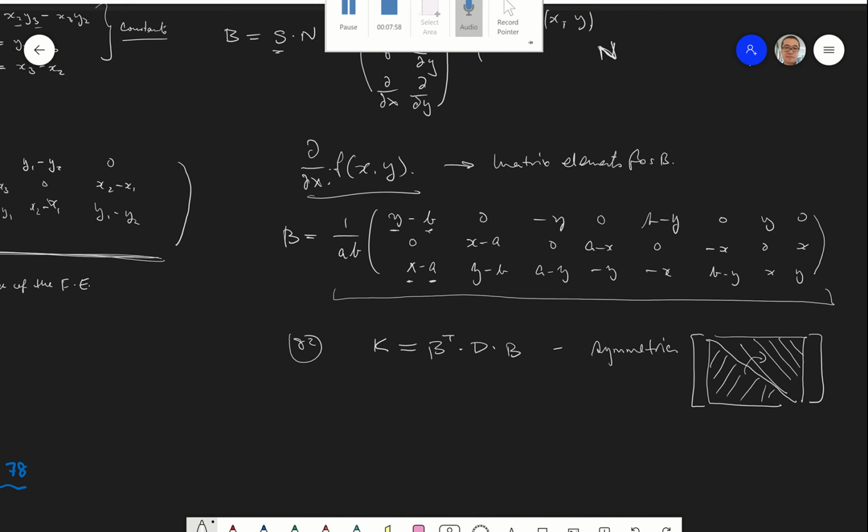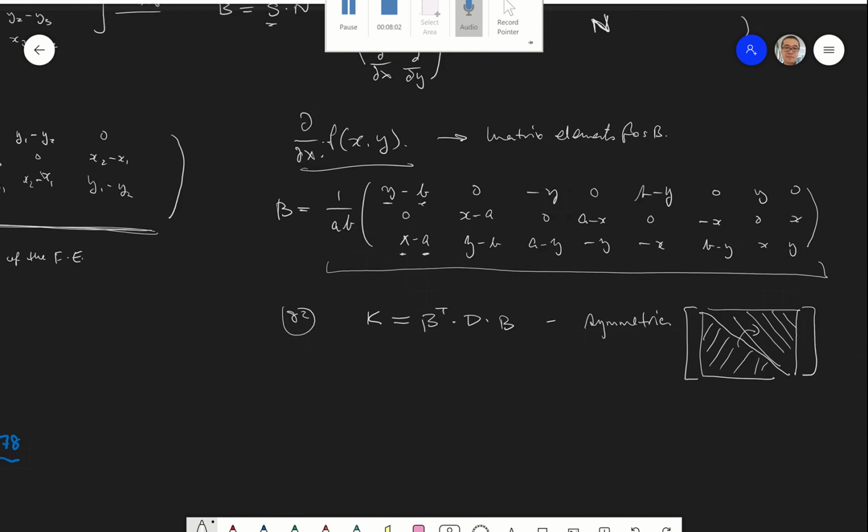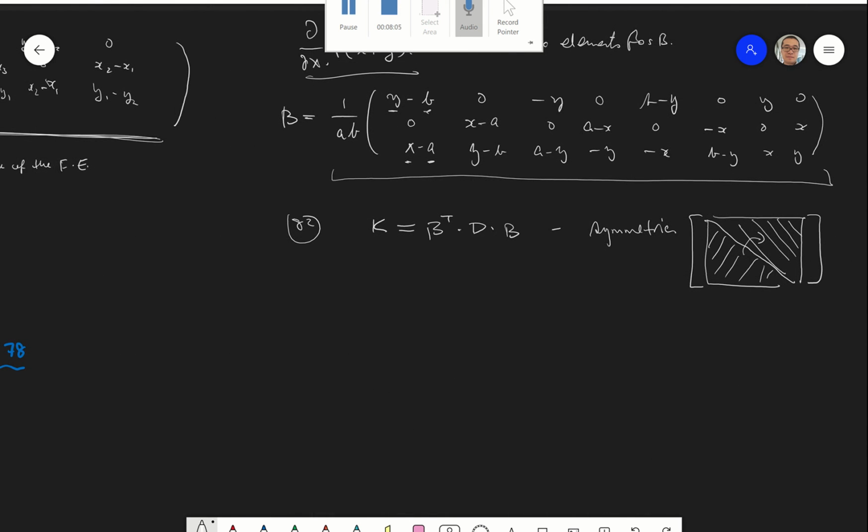Again, why is K important? Because go back to the very fundamental thing that we want to achieve in finite element analysis. It's not actually to work out this horrendous K matrix. Basically we want to use this K matrix to understand, okay, if a system or the finite element is subjected to an external load, which is this guy, how this shape or this structure will start to deform, right? And to be able to work that out, what do we need? We need this K value, right?